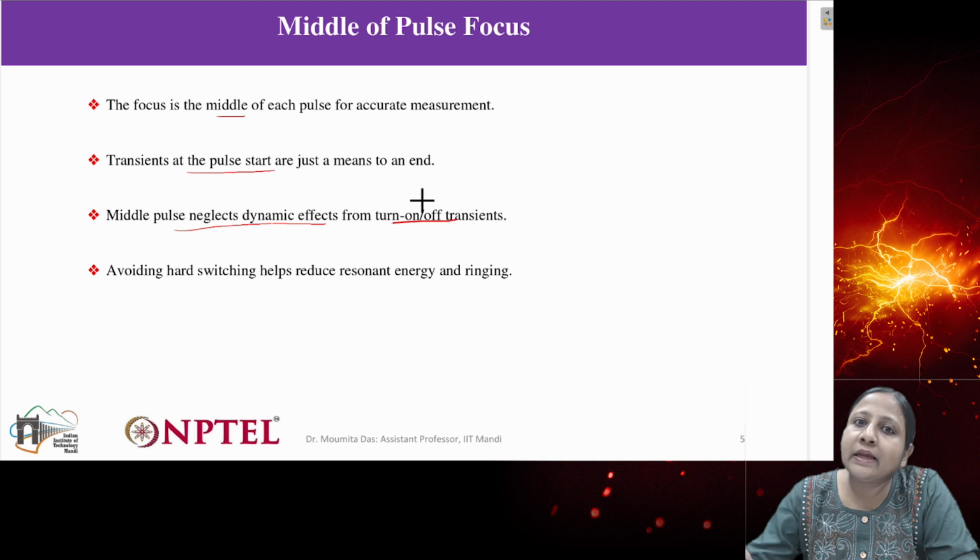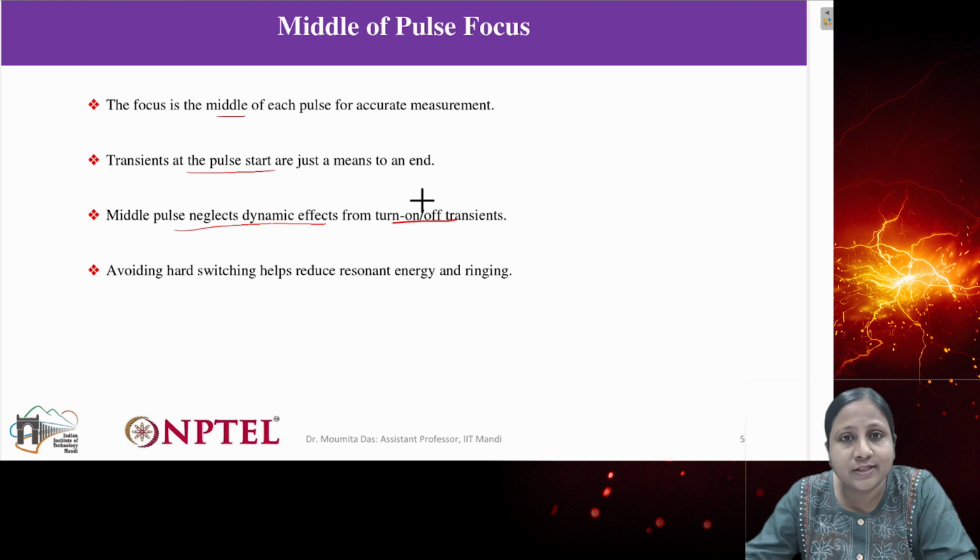Here the main concern is the maximum voltage and maximum current rating of the device, what the on-state resistance should be, and the different currents, basically the leakage current of the gate, the leakage current of the drain, or the current flowing through the gate. Those current values we will get.